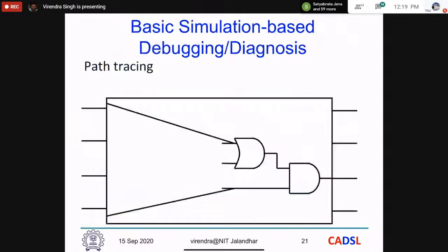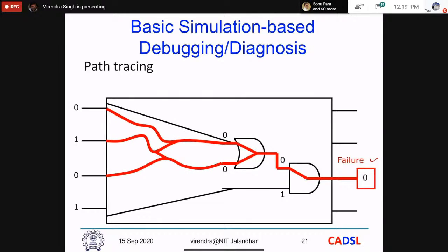Now what I do is, I do some simulation, and I trace these paths. It fails in some path, it failed over here, and then if I look at that back, I do simulate. In that case I will find out that this is my counter example for this input 1 0 1 1 0, it failed, and then 1 1 0 is propagating like this to this output. So this is my path.